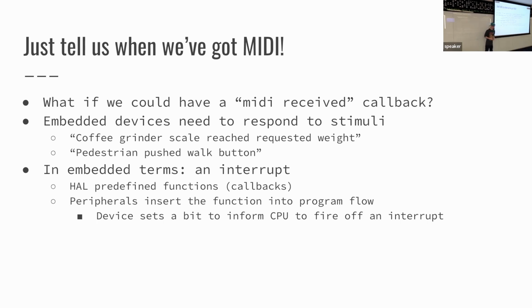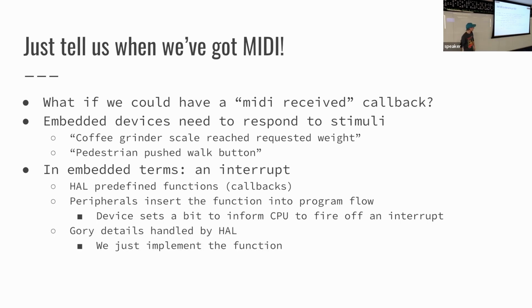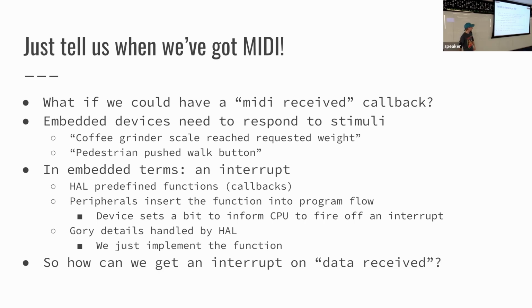So it's a very high priority type of callback in order to react to the real world. And you usually don't have to deal with things like the vector table of all the interrupts and reading registers. That's all handled by the STM libraries. So I felt like that just deserved a little background.